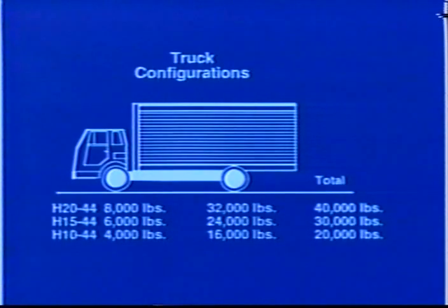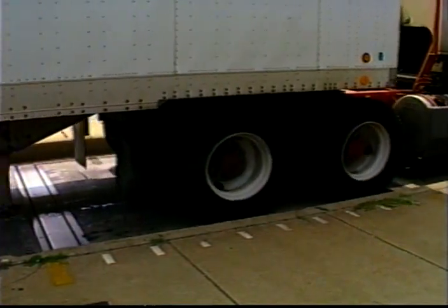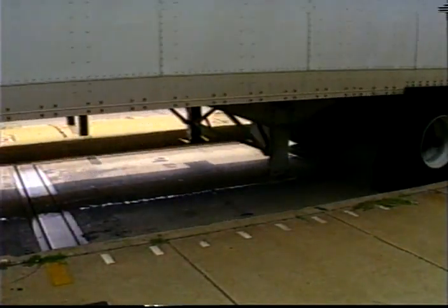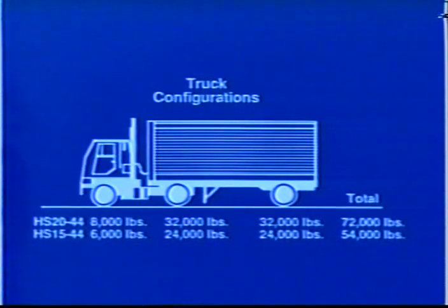To help determine the maximum live loads a bridge can carry, engineers have produced a series of hypothetical truck configurations. These configurations simulate the many actual vehicles which use the bridge. The live loads represented by these hypothetical configurations are concentrated at wheel locations on 2 or more axles. The effects of a series of vehicles is also considered. Standard truck configurations are identified by designations such as H15-44 or HS20-44, which define the load magnitude, number of axles, spacing of axles, and load distribution to axles and wheels.